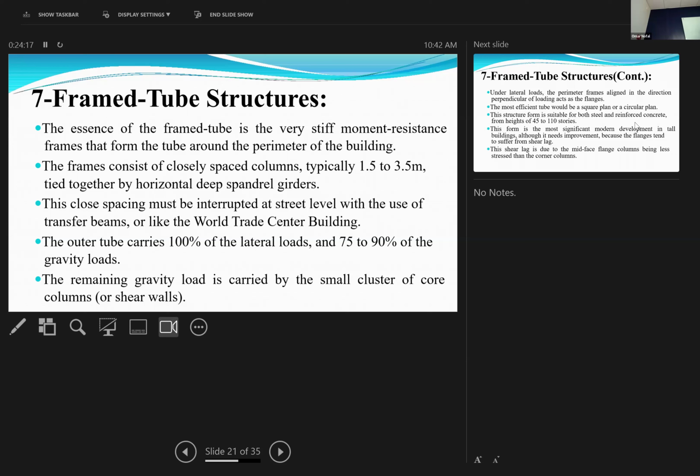But if this is not solid and has holes, voids like this, it doesn't look like that. Something is going to happen, which is the strains are going to be something like this, like this. So if it's a shear wall, it acts with very, very good efficiency. But if it's a perforated shear wall or columns connected with beams, you lose all this resistance. And why has this happened?